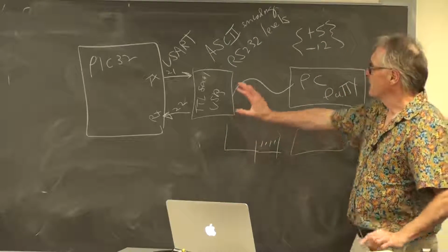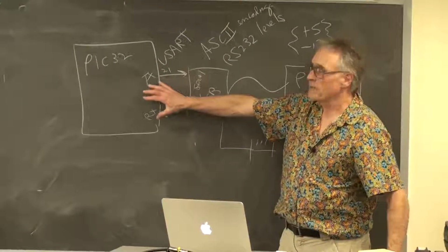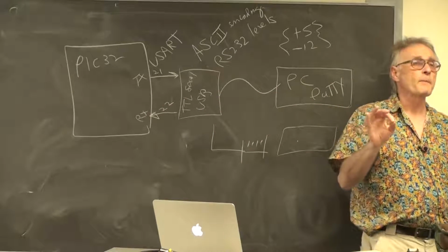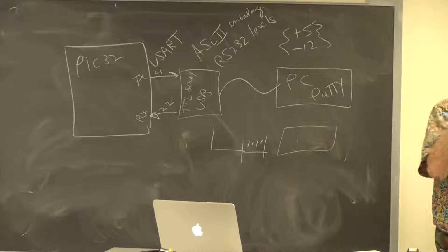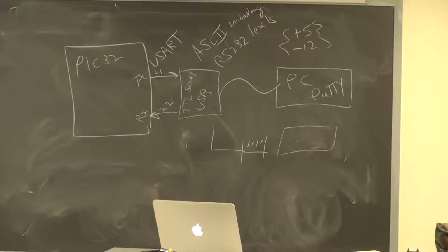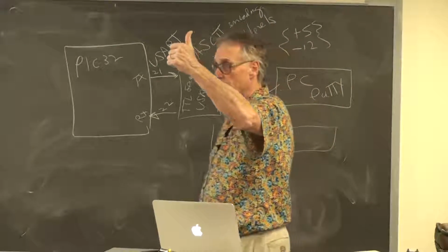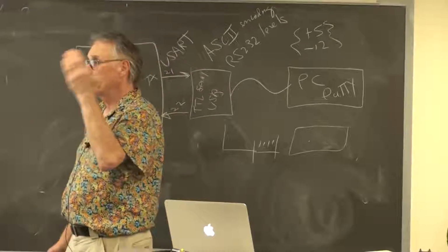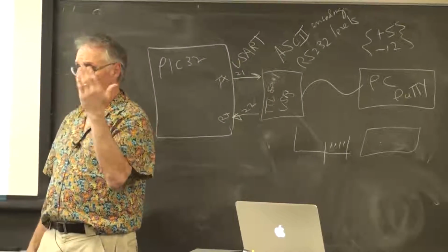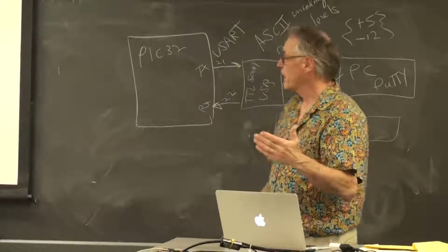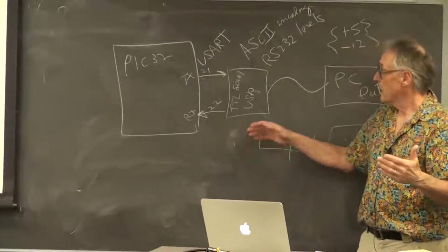As an aside, the transmit receive hardware on the PIC32 is yet another small coprocessor. When you push a byte into the transmit register and tell it to transmit, a separate piece of hardware fires off a clock and starts shifting bits out of a shift register for you in hardware at the predetermined rate, the baud rate, until it's done, and then stops.